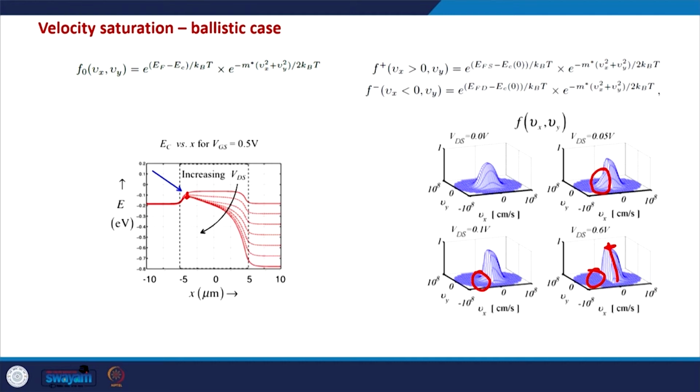So, in a ballistic MOSFET, along with velocity saturation, a slight lowering in the top of the barrier is also happening, and these two are important key points because they are fundamentally different from a conventional MOSFET, in the way velocity saturates there and the way the barrier is lowered. Okay, so I hope this is now clear.